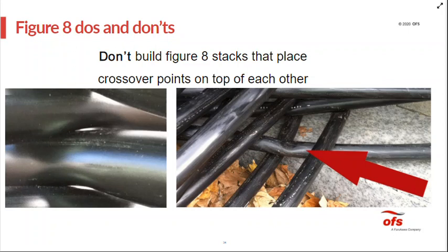And you can see in this particular circumstance that the compressive load from all the weight of those upper layers of cable was so high that it actually deformed the cable. So you want to avoid making a pretty figure eight stack. It's always better just to spread the stack out and spread out that load.